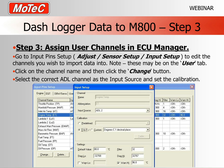which you can see down below. At the moment it's covered by another screen. That's our input pin setup screen. And then I've clicked on the engine temp channel, which is one of the ones I'm bringing across on the CAN bus. So I've double clicked here, and then that opens up our input setup for that particular channel. So you can see here it's called engine temp. And now I've clicked down on this little pull down button here, and I've selected ADL2 as the message that I'm going to use for my input pin.